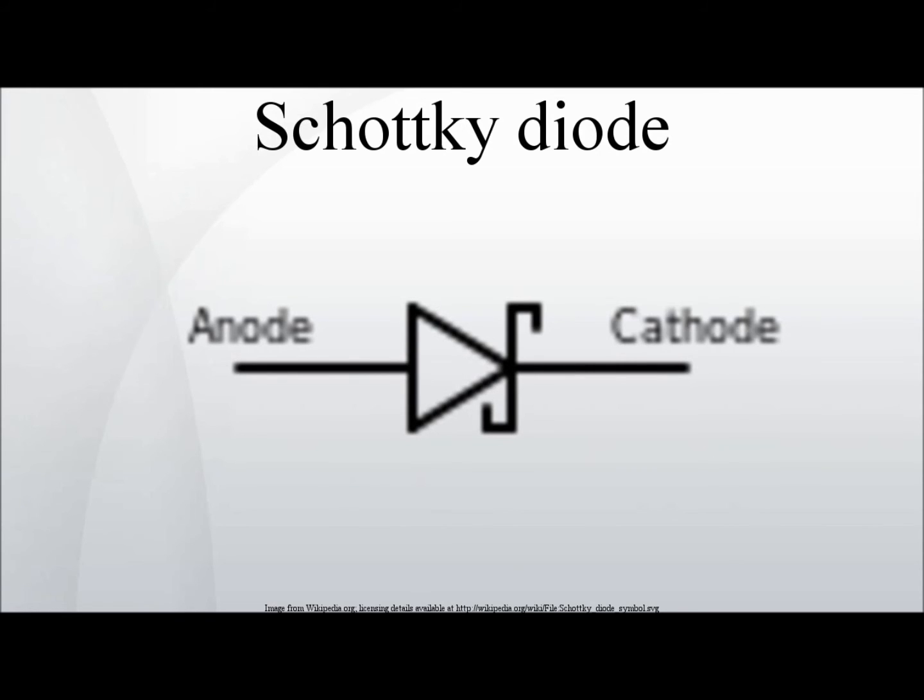With increased doping level of the semiconductor, the width of the depletion region drops. Below a certain width the charge carriers can tunnel through the depletion region. At very high doping levels the junction does not behave as a rectifier anymore and becomes an ohmic contact. This can be used for simultaneous formation of ohmic contacts and diodes, as diodes form between the silicide and lightly doped N-type region and ohmic contacts form between the silicide and a heavily doped N or P-type region.